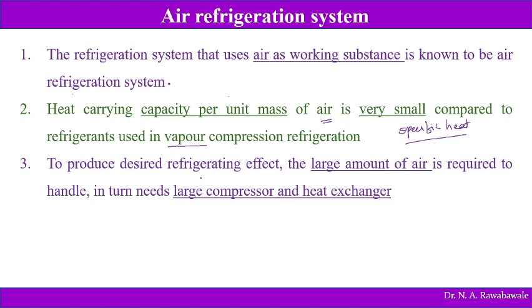Then to produce desired refrigerating effect, a large amount of air is required, because air has got small heat carrying capacity. Therefore, the system requires a large quantity of air, and to deal with a large quantity of air, the compressor and heat exchanger required are of larger size. So this is one of the disadvantages.